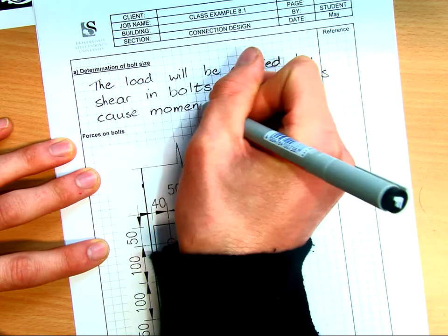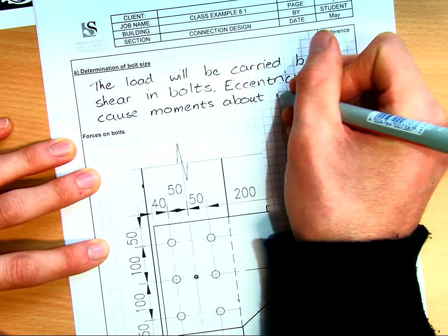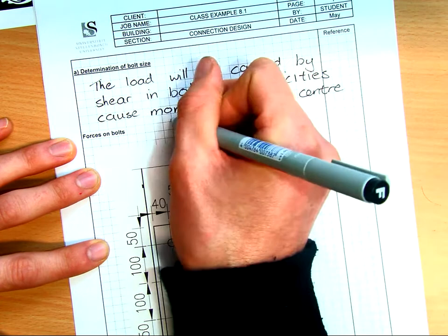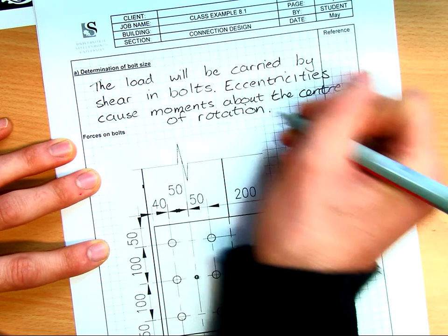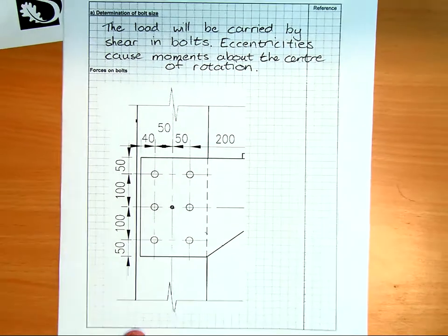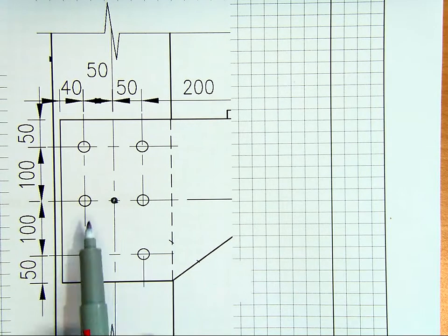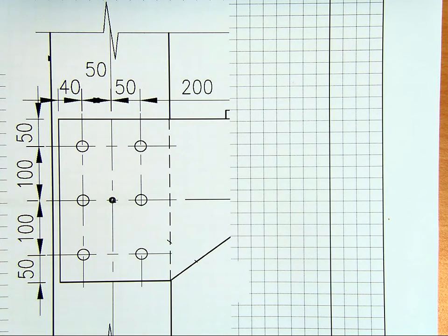We're going to have a look at the center of rotation now, because that's an important position to consider. Center of rotation. Now, looking at the forces in this connection, there is our connection, looking down at it, and we need to convert the forces we've got to something acting at the center here. In the same way we design beams and columns about their centroid, we are designing this about the center of rotation which exists there.